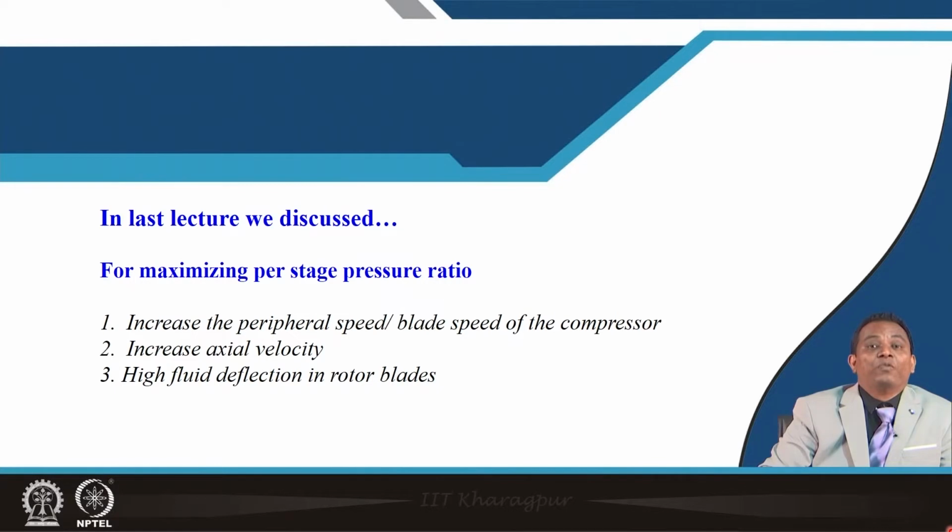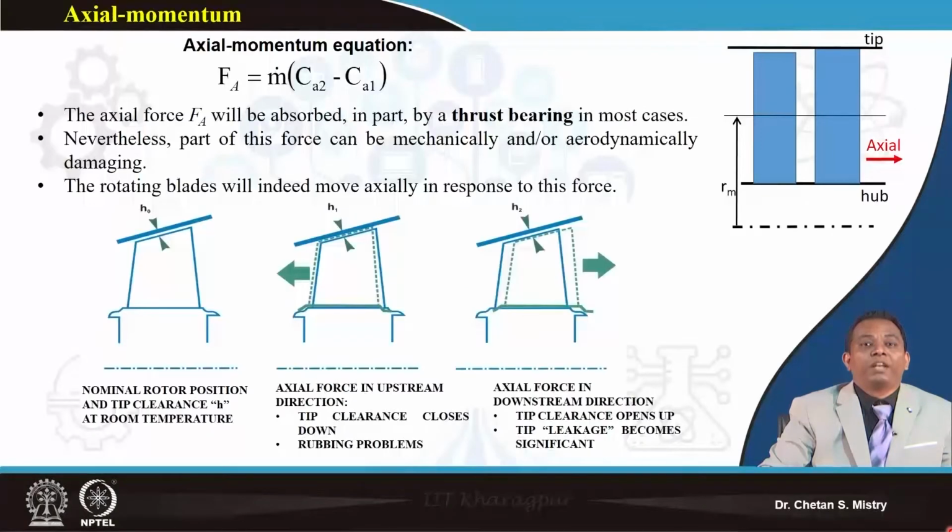Since we are working under an adverse pressure gradient, separation will happen on the suction surface or maybe the pressure surface of the blade. With a higher deflection angle for the rotor and an axial exit, the stator design also becomes very challenging. That's why people are finding different ways to address these issues. As we move ahead, we will discuss the development activities going on globally to address them. Now let's move to the next case.